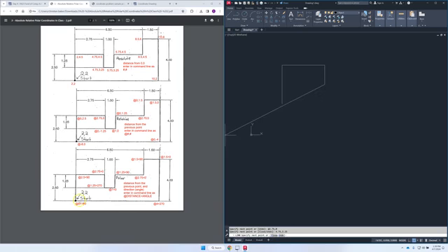And the very final input method we have here is polar. So polar, it lets you type a distance at an angle. So we add in the less than symbol. For AutoCAD, that'll be the angle input method.